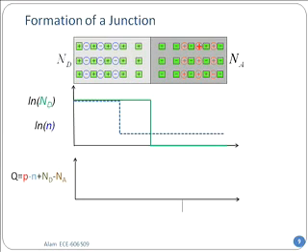The net charge, you can see, will be QND approximately, because up to the beginning of the depletion region, N is perfectly balanced by ND, and therefore you have zero net charge. So I haven't drawn anything up to that point. Then the subtraction from the green to the blue in the depletion region is essentially equal to ND, because most of the electrons have gone away from that region.